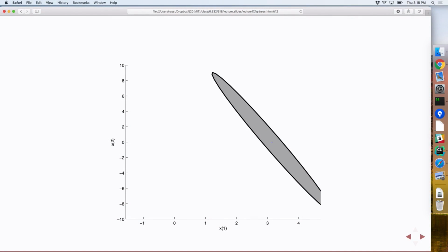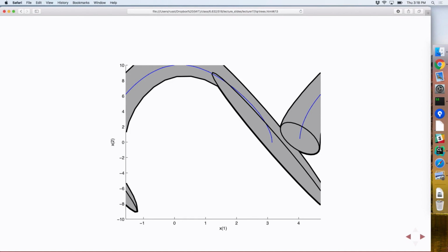Okay, so you've got your initial condition at the end. You sample randomly across the state space. If the sample lands inside a gray region that was already covered by your controller, you can throw that one away. You don't need that. Keep sampling until you end up in the free space. When you do end up in the free space, do trajectory optimization to try to get you back to the tree. Right now the tree was initially just the point at the upright. The trajectory optimization may fail because it's not a global method, but when it succeeds, you add that trajectory to your tree.